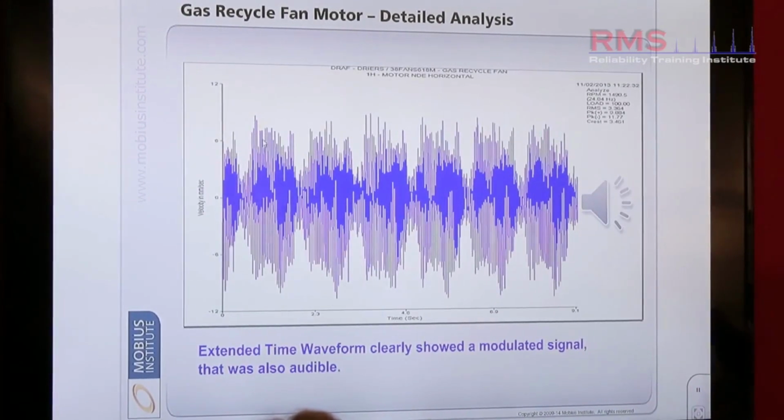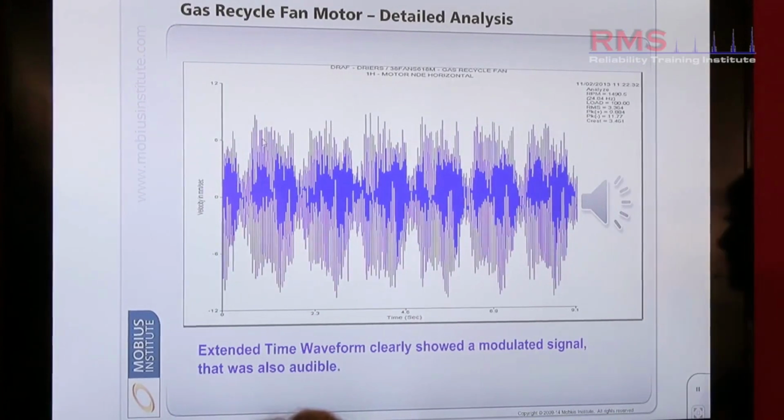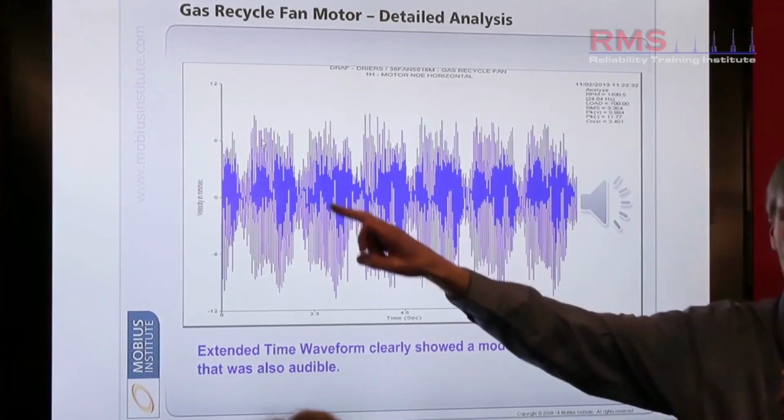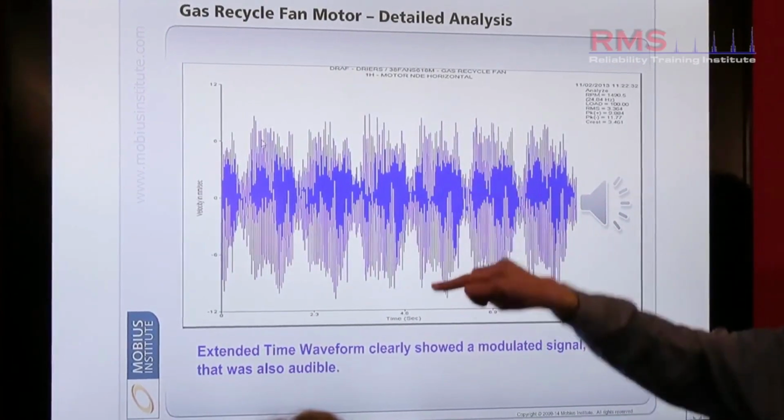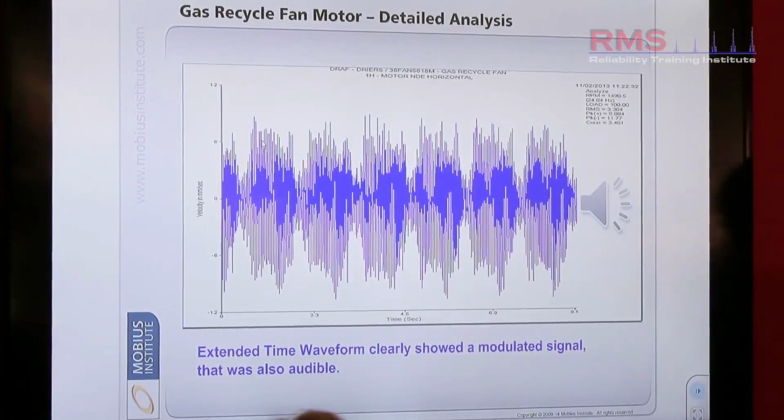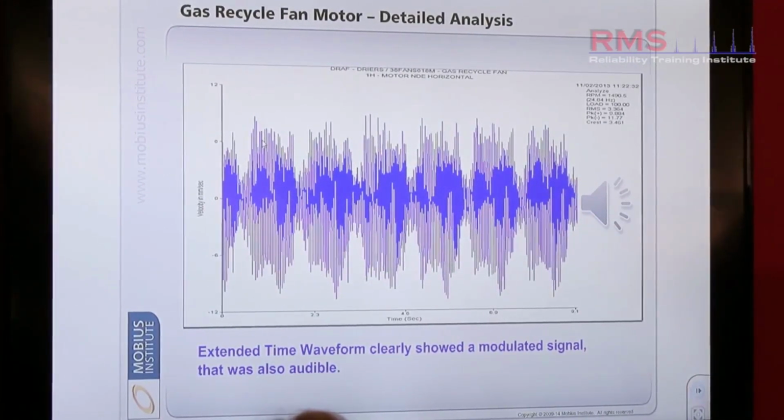And you can see here, this is the signal in raw form, very complicated, very difficult to relate to, but the picture is it goes strong, it goes weak, it goes strong, it goes weak. The amplitude's changing, that's why there's sidebands. The harmonics are there due to distortion.